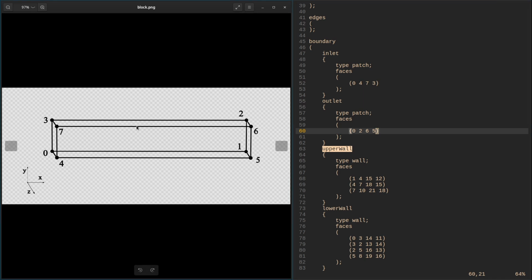For upper wall, the symmetry plane here, you have the freedom to change these names here to make it more descriptive for your problem, if you want, but I keep it here. We need to change this type from wall to symmetry plane. These two here are good. I keep them.